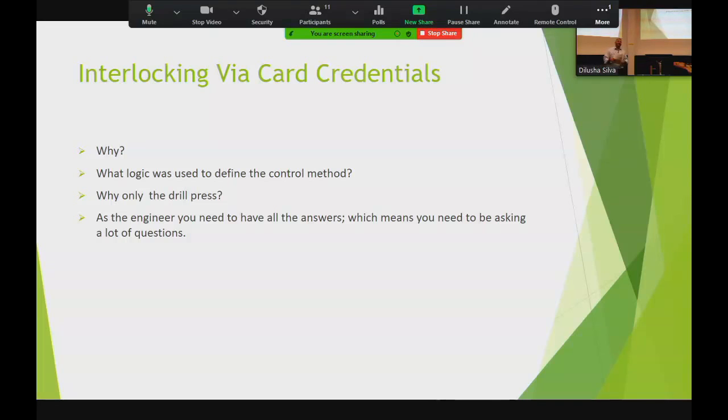But if you turn around and said, okay, I'll challenge you with this: put the card reader on the wall, and I've got a contactor low down, which is switching the power point that's protecting that drill. I can then unplug the drill, move it to another space, give it to a lecturer or a technician who doesn't need the same level of control, and use it somewhere else. I can also bring in a new device, plug it in and use it straight away, because the interface is part of the fixed installation, not the portable installation. So you can use it for different bits of equipment.